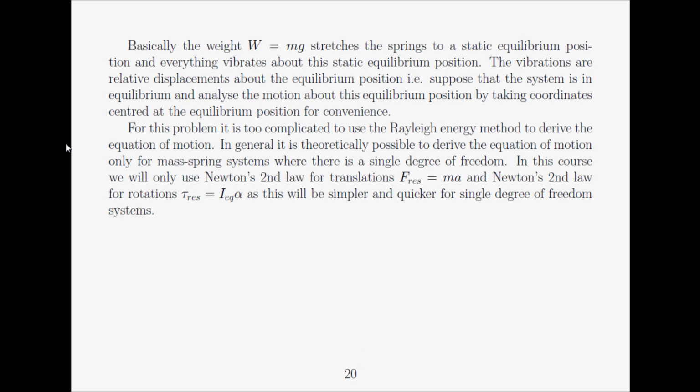When we do the analysis for vibration problems in particular, we will therefore usually disregard the effect of weight. In other words, the gravity force, because it will stretch the springs, the system will reach some sort of static equilibrium position, and then everything will vibrate about the static equilibrium position. So vibration problems are essentially relative displacements about some equilibrium point for the system.